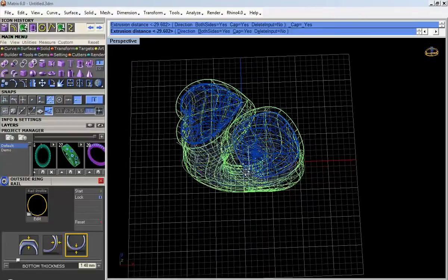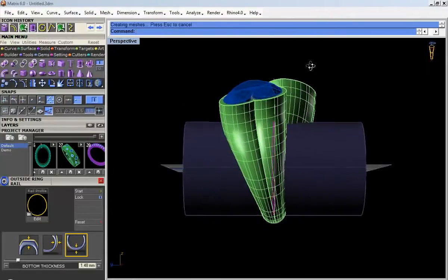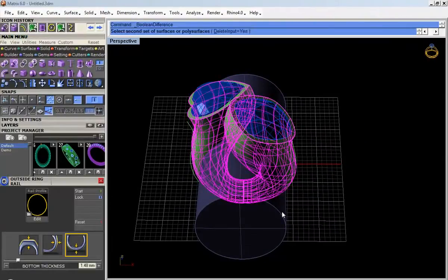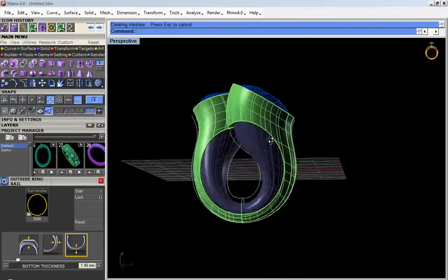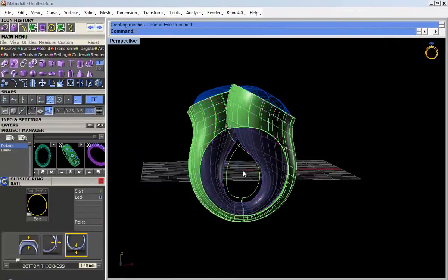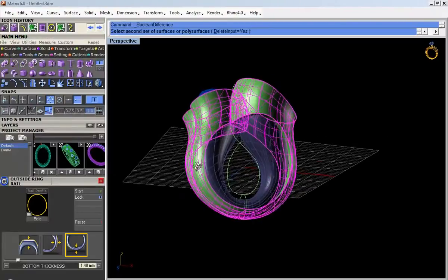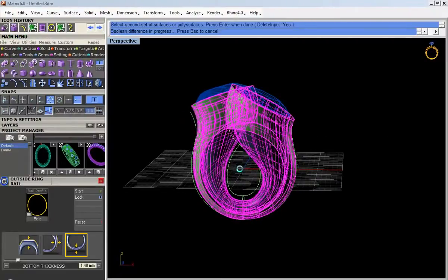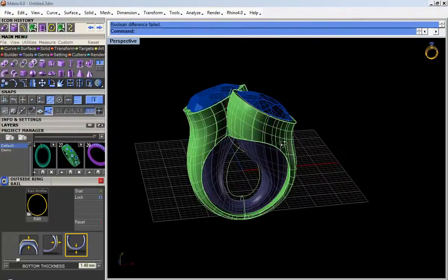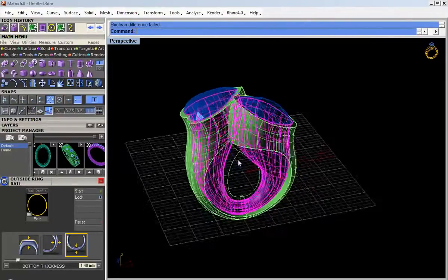So I extruded the curve like this, select this. Yeah, it did. It's good. So now I'm going to try to do boolean on this also. It failed, right? Why? That's because these are touching each other, that's the reason.